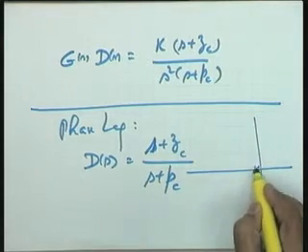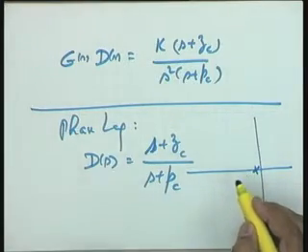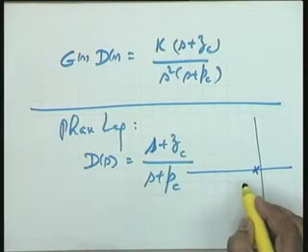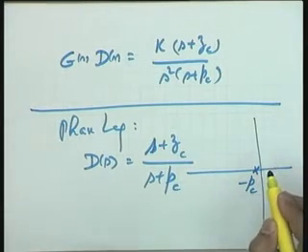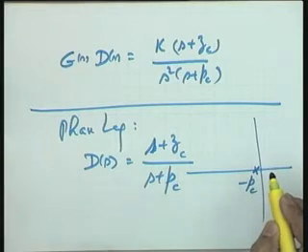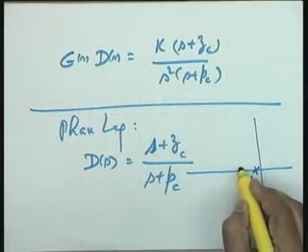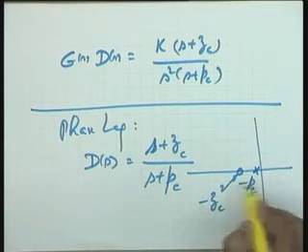So let me add some extra degrees of freedom into my controller. I can of course place my pole at the origin, but to get extra degrees of freedom, I place the pole at S equal to minus Pc, where Pc equal to 0 is a special case, and a zero I place at minus Zc, which is close to the pole.